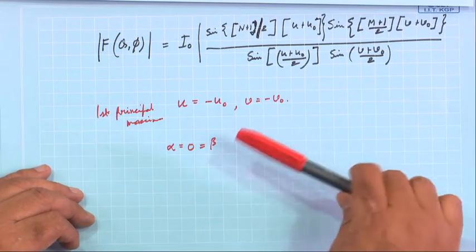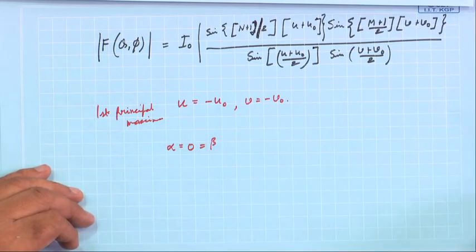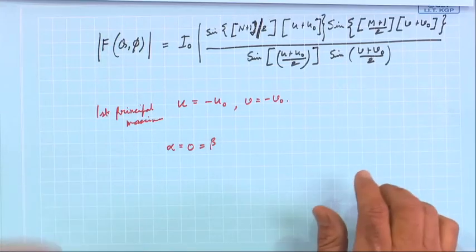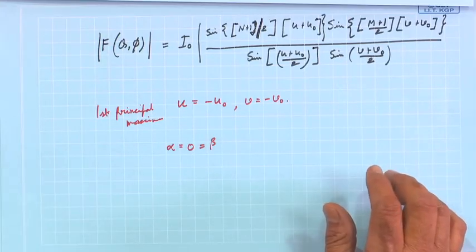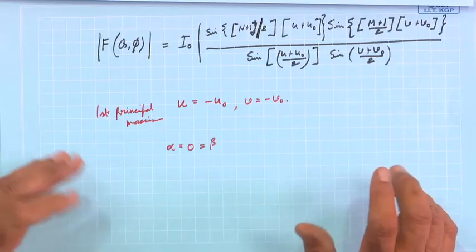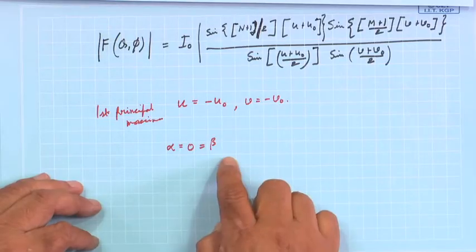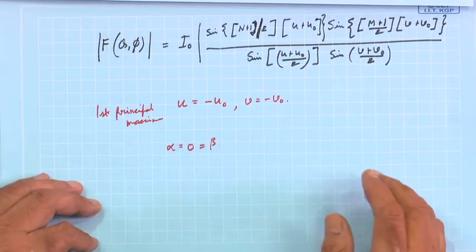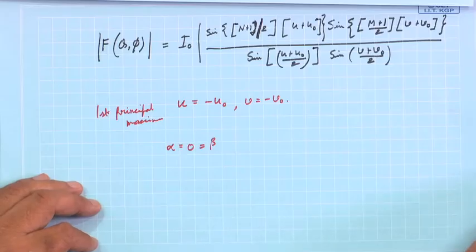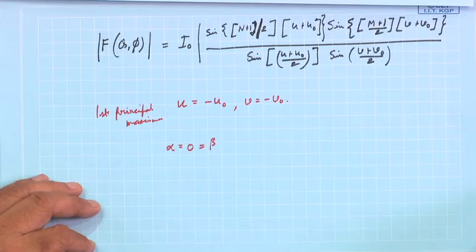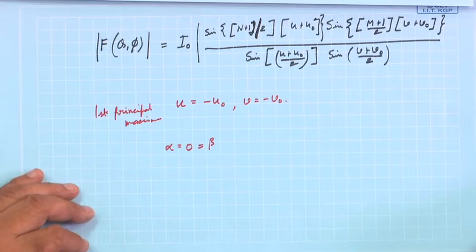For suitable values of alpha and beta, the beam can be directed in any direction. So, this is called the concept of phased array, that if I want to move the beam, that can be done by putting some values for alpha and beta. So, in whichever direction you want to point, based on that alpha and beta values can be put. Since this is done electronically, that is also called electronic scanning.